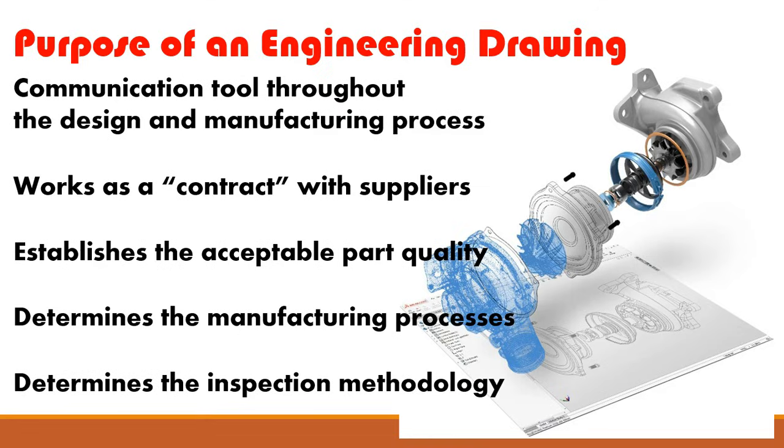And last, it determines the inspection methodology. Again, it goes back to how you're going to clamp the part down using your GD&T. If you want to see more about geometric dimensioning and tolerancing, I have a couple of videos that you can watch and a whole playlist of GD&T rules and fundamentals. But it also lets you know how you're going to clamp the part, and what features have to be held in relation to which, and the entire inspection process can be dictated through the blueprint.